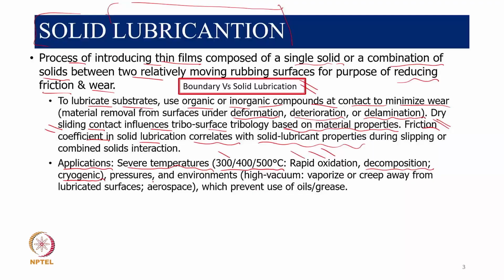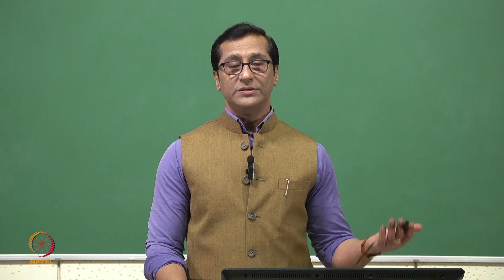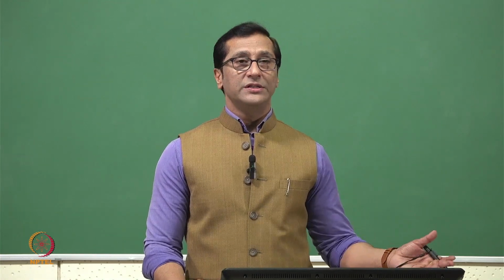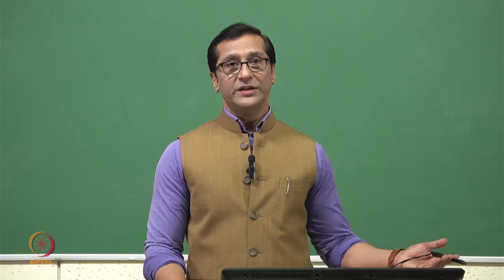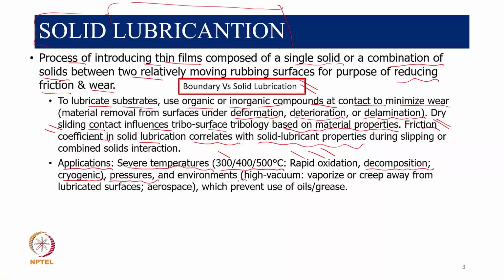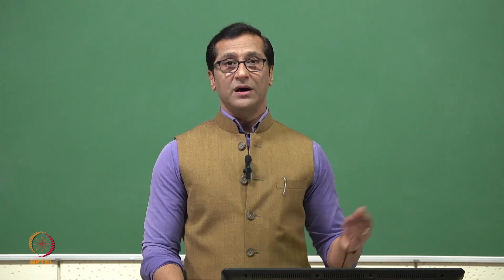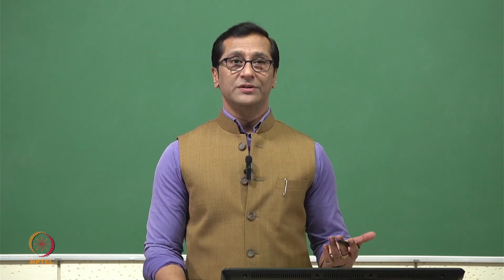At extremely high pressure, that's also a problem for liquid lubricant, which will get squeezed out, and then there will not be any lubricant at the interface. And a more important factor is the environment. When we talk about high vacuum, the liquid will get vaporized, or it will not be at the surface.